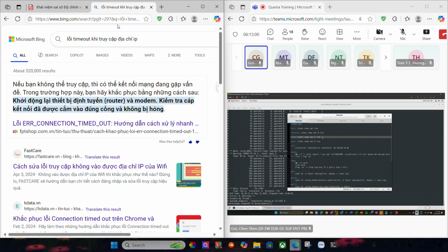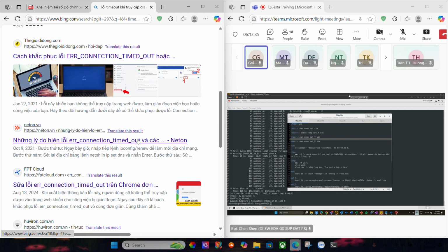we should do trap mode first to clean up the first X, and then we do resolve mode, and then we do pass mode so that we can ensure that there's no X propagated or any X issues in the simulation design itself. So, yep, that's all for X propagation. Now let's move on to CDC and linting. If there's any question on X propagation, you can ask now. If not, then we'll move on to CDC and linting.